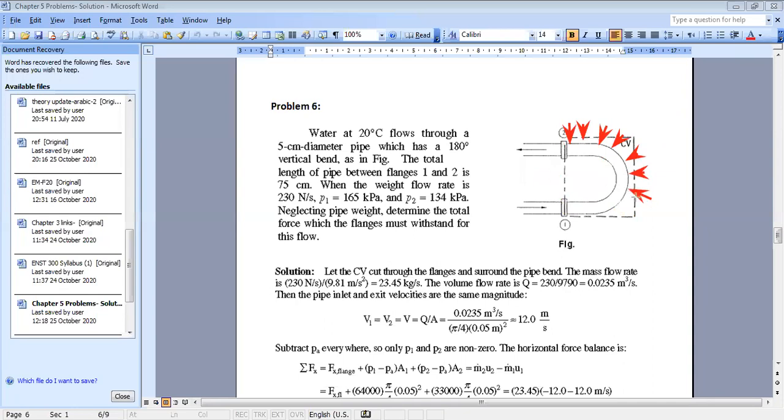But as a result it's the same effect, because look, pressure is everywhere. So PA is everywhere, and just at this location you have a different pressure. So also here as a resultant, and whatever the shape of your control volume, okay? When you do the summation of forces, the atmospheric pressure on this side will be cancelled out by the other forces. So you will only have P2 minus PA on this side remaining. Because whatever your shape, if you have a closed shape like this, you can have any form. I don't care for the form, any geometrical shape, and you have atmospheric pressure everywhere. What will happen? The total pressure force will cancel out, because if you do the summation of forces in X and in Y, they will cancel out.